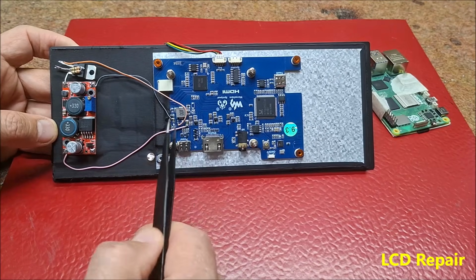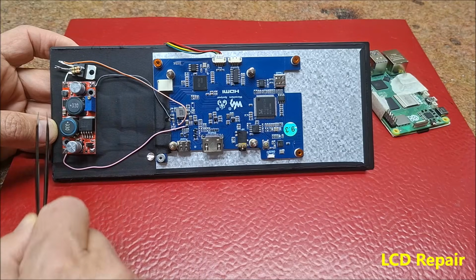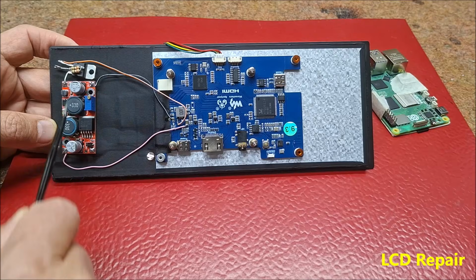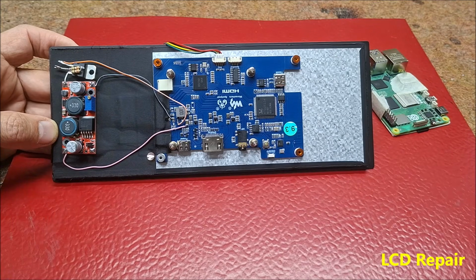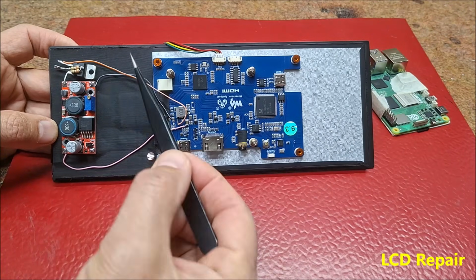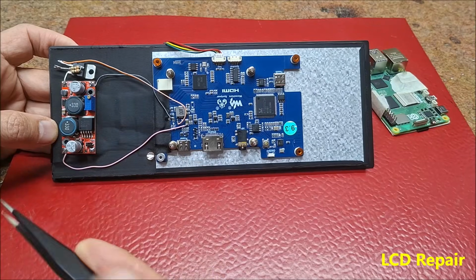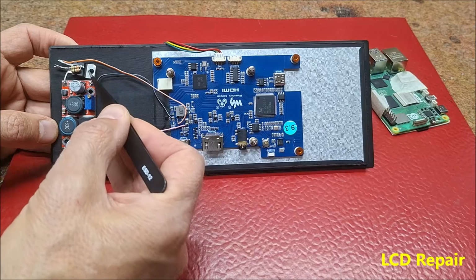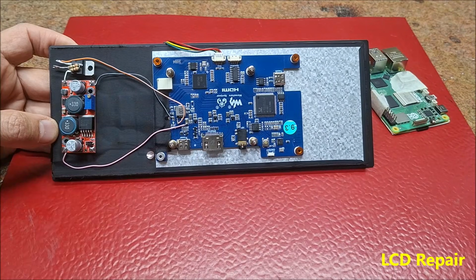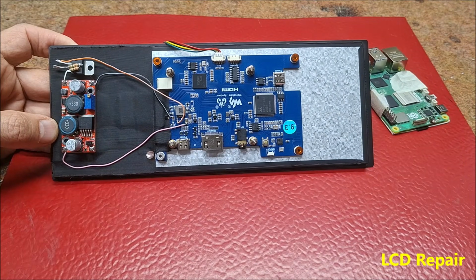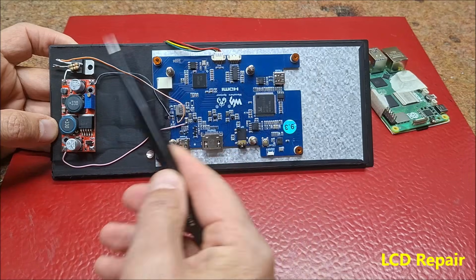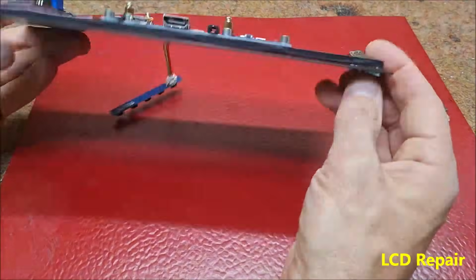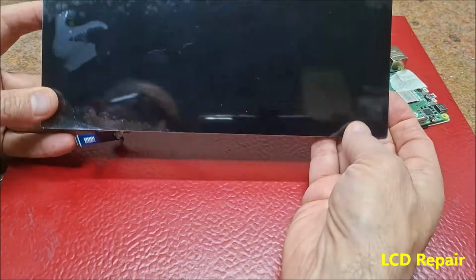Then, as a more elegant solution, I connected a cheap external boost converter module from 5 to 12 volts, and with an LM317 I limited the output current to exactly 60 milliamps with this 19 ohm resistor. This way I got the display back fully functional, although its price is around $100.